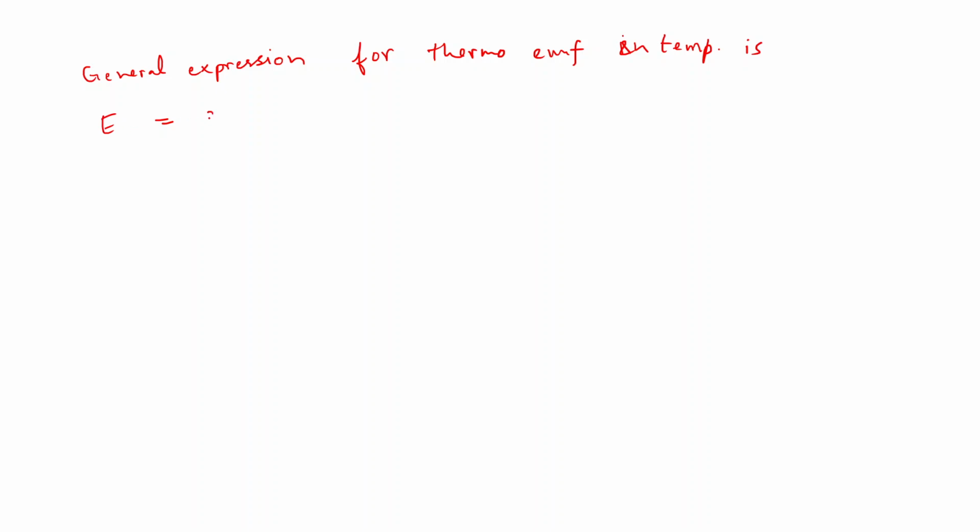Scientifically, it is known that the general expression for thermo EMF in terms of temperature is given as, this is the thermo EMF generated because of heat, AT plus BT square plus CT cube and so on, where A, B, C are constants and they depend on the kind of material we are talking about or the type of thermocouple we are considering, and this T is actually the temperature difference.